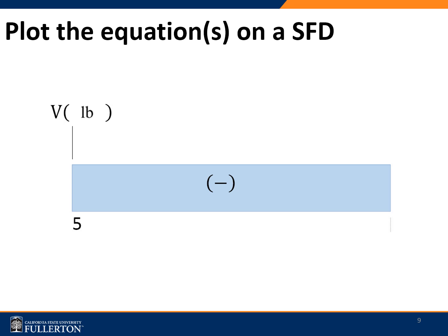Also, any point where the shear force diagram crosses the x-axis will be a maximum or minimum bending moment. The bending moment will be discussed in another video. The shear force diagram should always equal zero at both ends. Lastly, if somebody asks you for the shear force formula, that's simply that the sum of the vertical forces should be equal to zero.